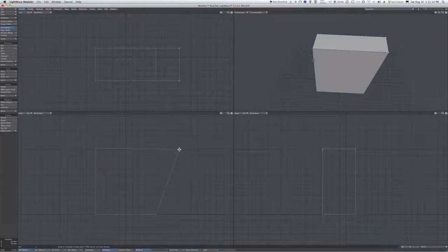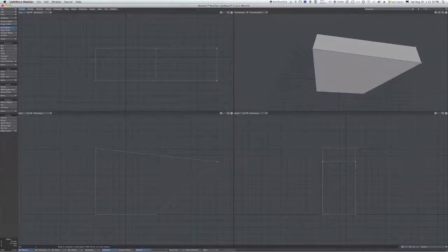So you need to think about that when you're designing something. If you wanted to print this with this way down here, this could be an issue. I think right about there is about 45 degrees. Okay, 45 degrees is on the borderline of, yeah, it'll print, no, it won't print, depending on your printer's capabilities.